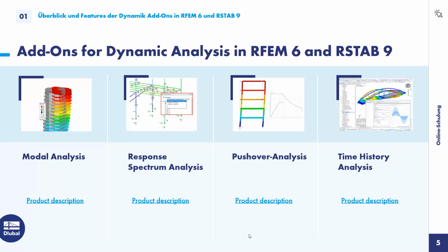The response spectrum analysis itself combines the response spectrum with the eigenfrequencies and creates a state of the system, let's say. It could be created by applying equivalent loads, or the equation can be solved directly to get the internal forces as well as the deformations. That's done currently within RFEM. You just select the response spectrum and some important modes for it, or let's say 90% of the model mass you would have to select.